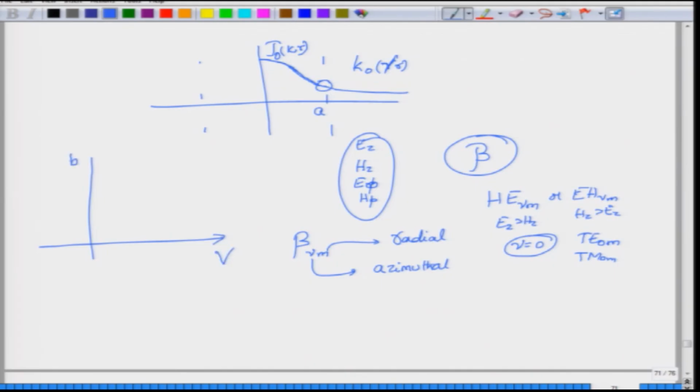You may have normally seen these curves. You can actually generate these curves of what is called the normalized propagation constant B and the parameter V, and the curves that you obtain will look something like this. This would be the curve HE11, which is also called the LP01 mode. This is called a linearly polarized mode, and this is an approximate mode, obtained by what is called the weakly guided approximation. We will not go into details, but this is the mode curve.